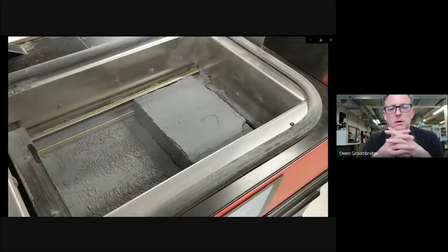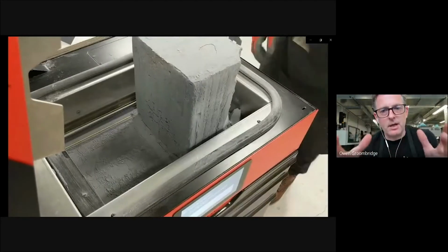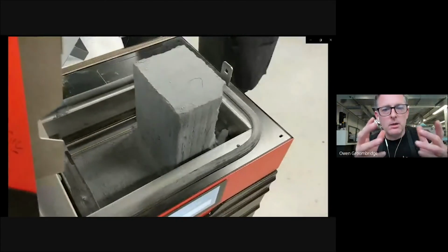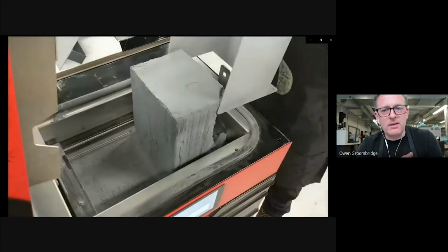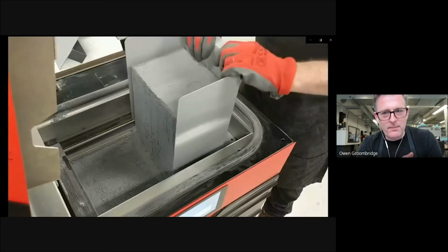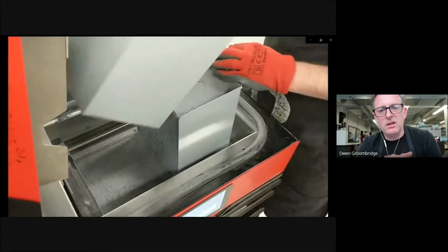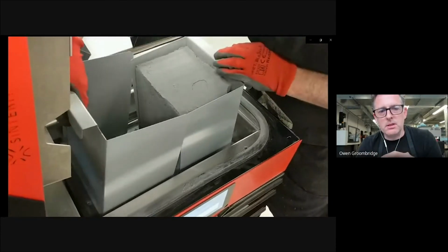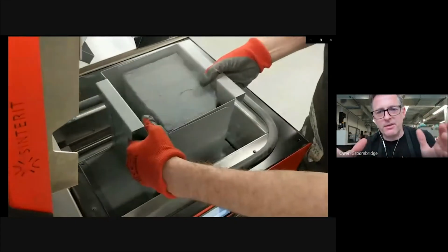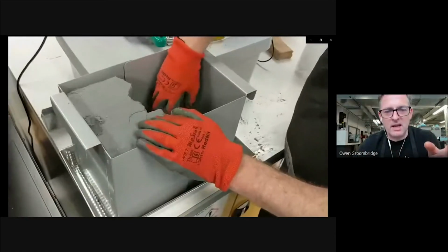All right. So what happens is that once you finish printing, and this was a big object I printed for another SCP student, that horn type thing that I showed you with the fusion demonstration, you have to get this block of powder out, and bear in mind, it is still powder. Now, when I was saying self-supporting materials don't need support structures, this is why. The feeder arm pushes the powder over the print, the laser activates, it sinters the material, and then the print head drops, and it repeats the process again and again.